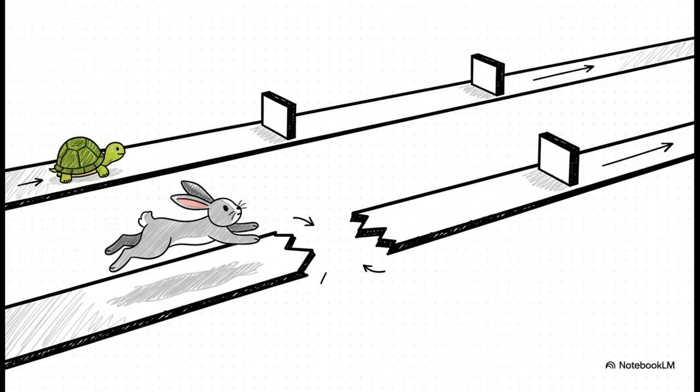They're taking the cautious, steady route. Step 1, perfect the new GAA transistors. Step 2, later on, integrate a new power system. It's a reliable step-by-step evolution. Then you have Intel. They're going for broke. They're making this super aggressive leap to do everything at once. They're introducing their version of GAA and a radical new idea called backside power delivery.